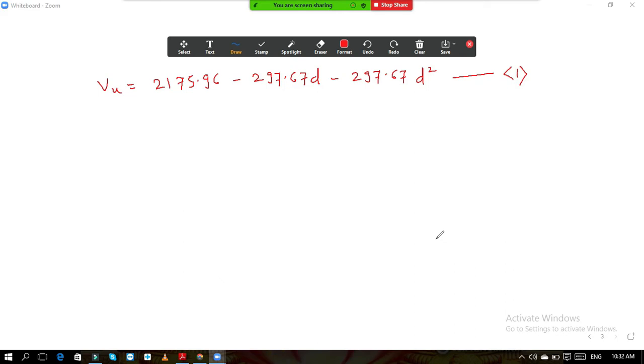Okay, so now this is the total shear force. Now from this total shear force, some of the shear force is resisted by the concrete. If we want to avoid providing shear reinforcement, we have already studied this shear reinforcement in detail while designing the beams in DCS 1. Now I am just revising this. If we want to avoid the shear reinforcement, it means avoiding the placing of stirrups. Generally we don't place stirrups in footings and in slabs.